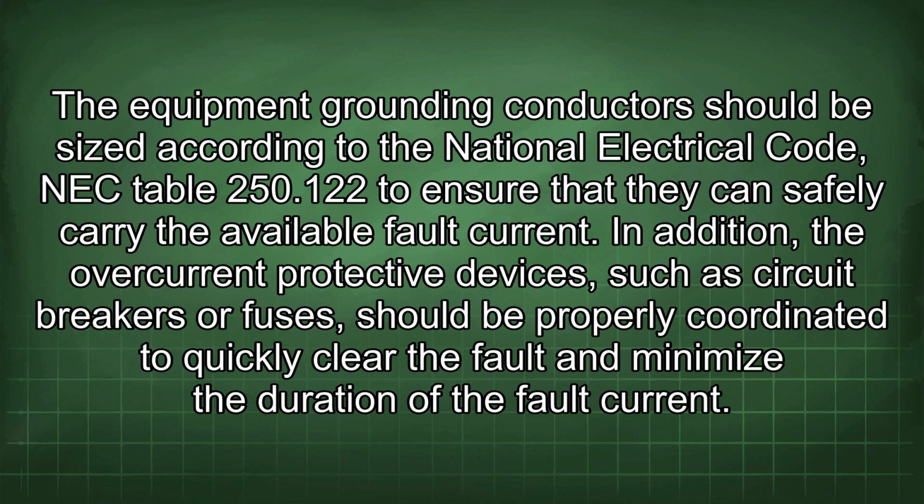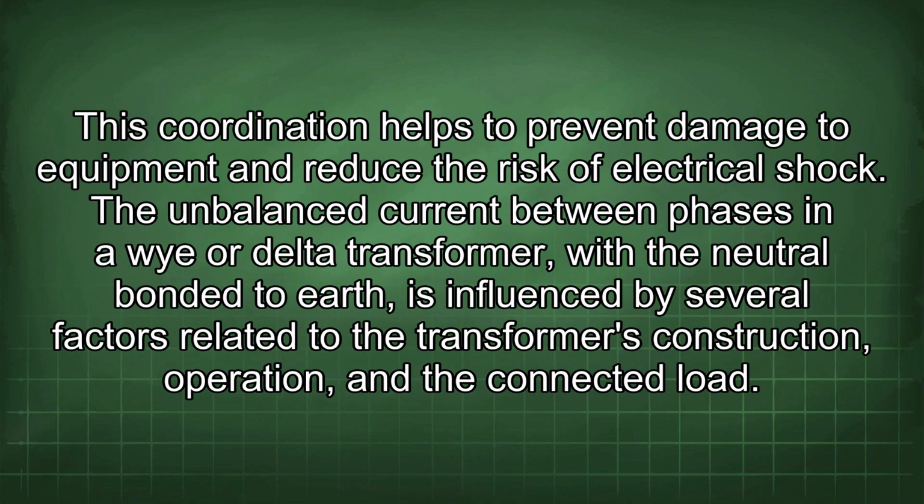In addition, the overcurrent protective devices, such as circuit breakers or fuses, should be properly coordinated to quickly clear the fault and minimize the duration of the fault current. This coordination helps to prevent damage to equipment and reduce the risk of electrical shock.